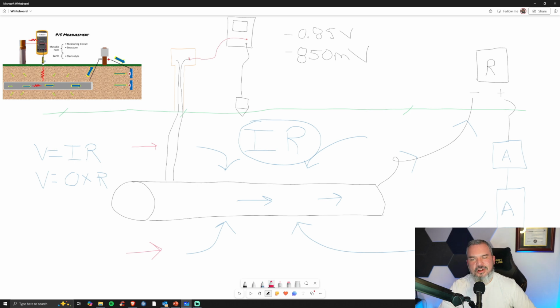If I just turn off my blue current and take a measurement, have I eliminated the voltage drops? Unfortunately, no. If red current is on, no, we haven't. Aha. Okay, well, let's call him and see if he'll turn his rectifier off as well. Maybe we can turn them off and on at the same time and get those measurements. That's possible. So we can eliminate that red current.